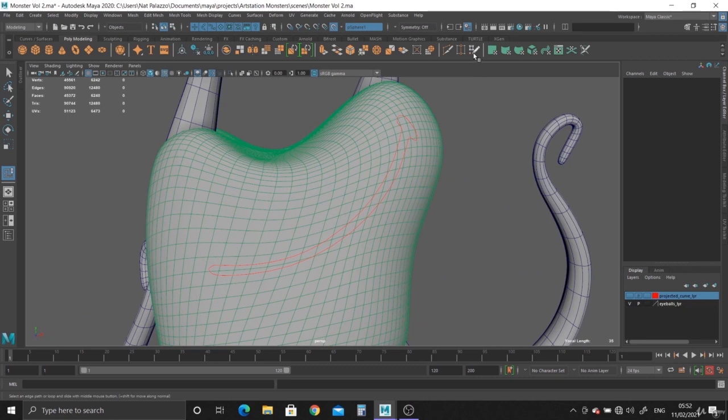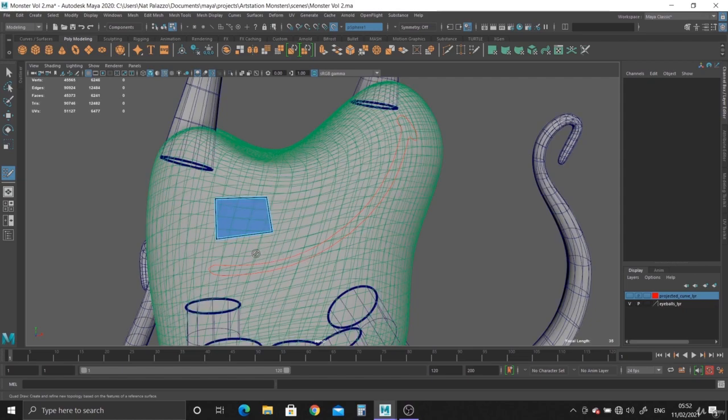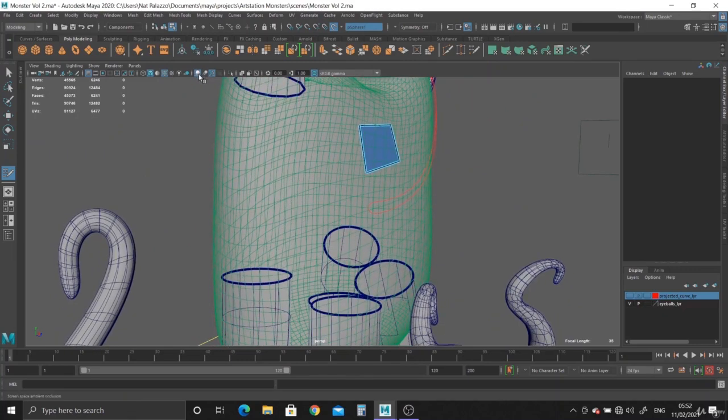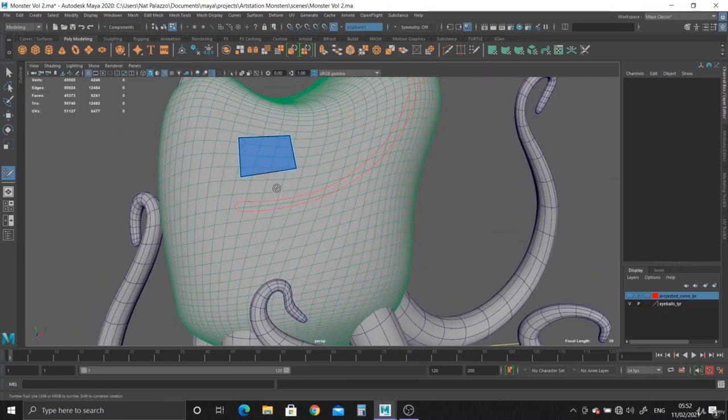And if we select this tool here, quad draw tool, we can actually just click dots on it, and then if you hover the cursor between the 4 dots and hold down shift, you get this green illuminated shape, and then click and you've created a polygon. You see now the minute it's pretty transparent, and that's because we've got ambient occlusion switched on, so just switch that off and there you go.